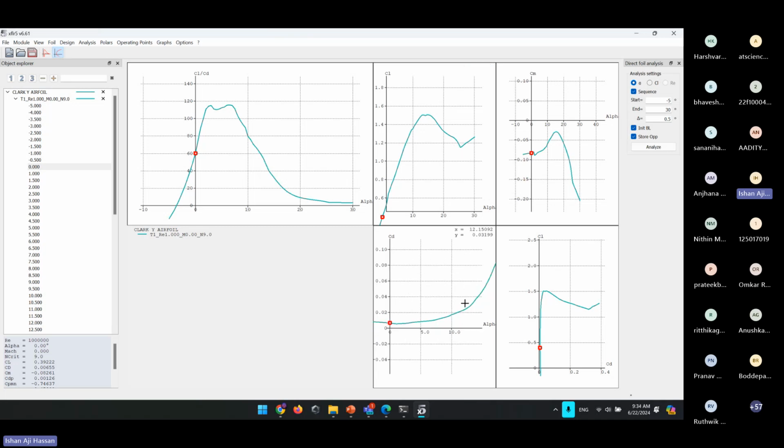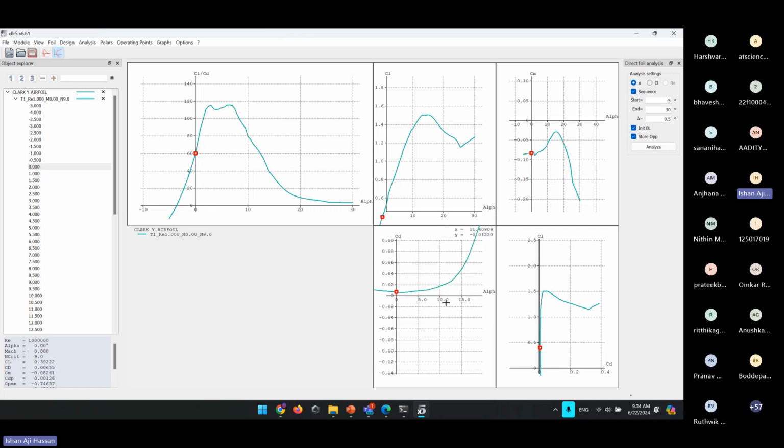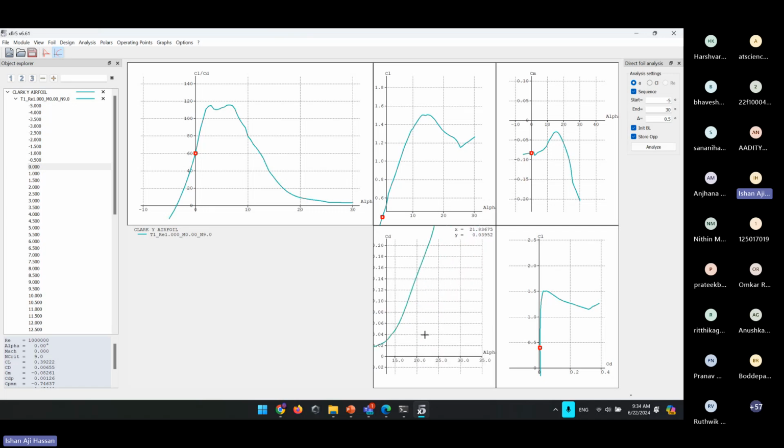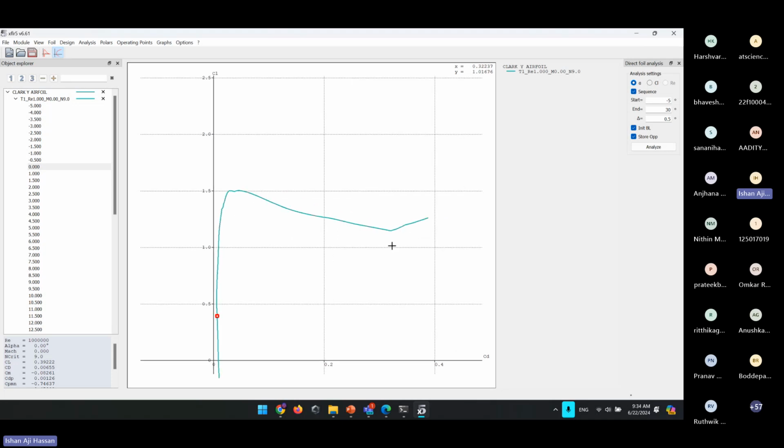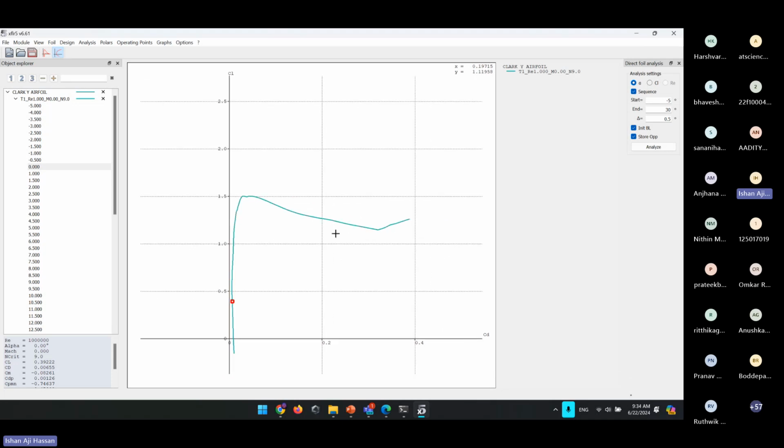And from 7 degrees to 25 degrees, you'll have this exponential increase of CD. You'll have such a large range of CD. It is going from almost 0.01 to 0.3 or so. And that is what you are seeing here. Over this small range of CL, you're getting a large range of CD, 0.01 to almost 0.3 or so. That is what we're seeing in this section. So it's just a representation of the other graphs together. That's it.